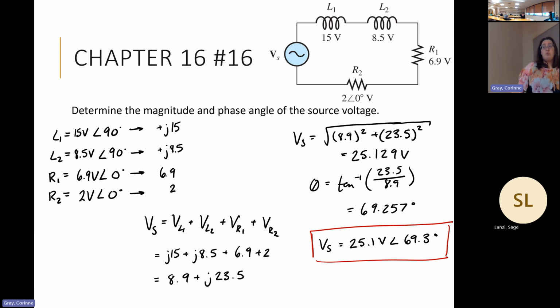So again, a lot of the same rules that we saw for RC apply here. The equations look different. For the capacitor, it would be negative 90 degrees instead of positive, so we'd have minus j. That would also mean that our angle is going to pop out in that fourth quadrant. So please be careful when you're dealing with this. For the exam, it's just going to be capacitors. But for the final exam, you can have both. And when we look at RLC circuits, we'll have both as well. We need to keep track of what signs correspond to what.